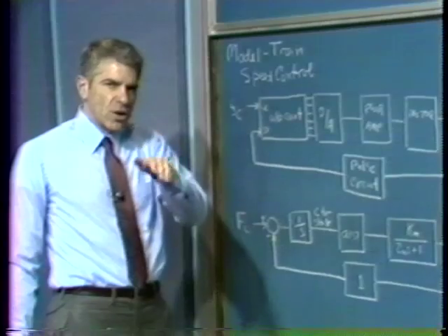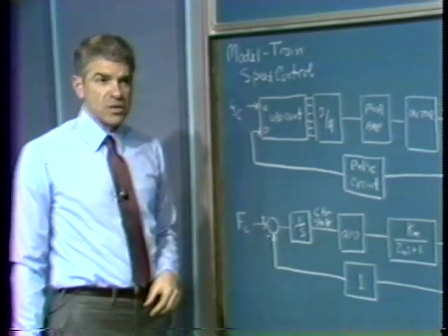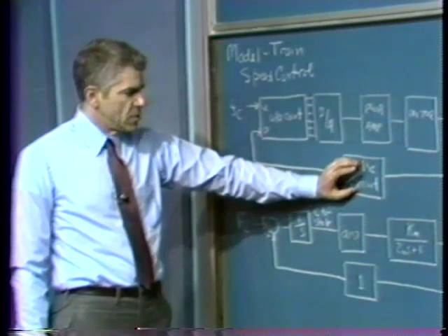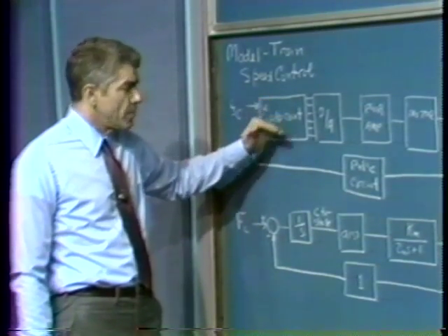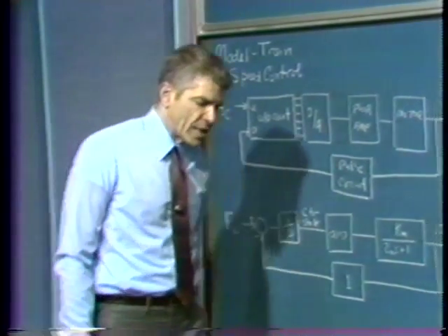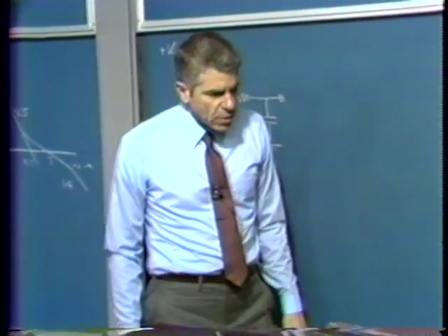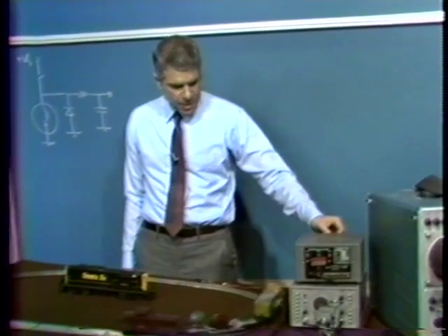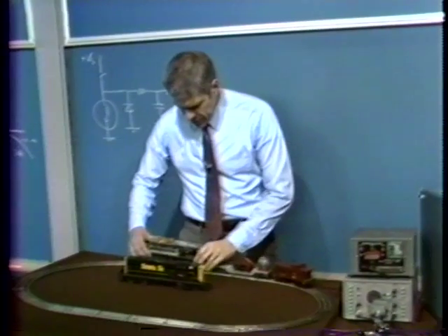Similarly, when we round the corner and go downhill, the motor overspeeds just a little bit. The load is greatly reduced when we go downhill. We get additional pulses off the commutator. That decrements the up-down counter. We apply a smaller voltage to the motor, and so we get that sort of speed control. We can look at the engine and see at least some of the hardware that allows us to do this.